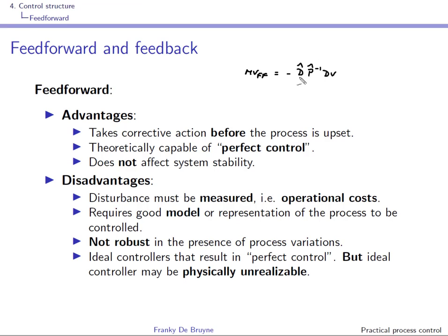In practice, you have to use models of the input-output dynamics, P, right, and a model of the disturbance dynamics, D. In the background, what will happen, because you have to go through the process, is that you have an inversion of the process dynamics.